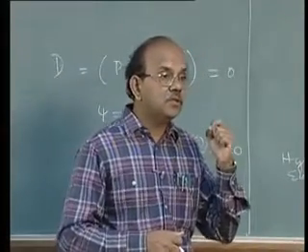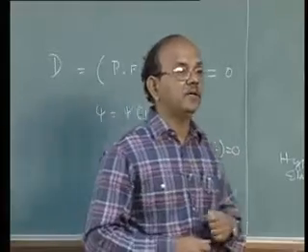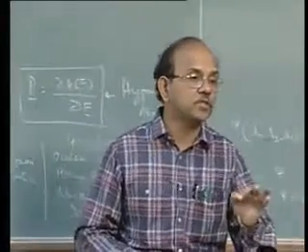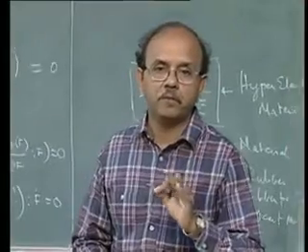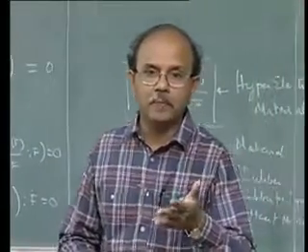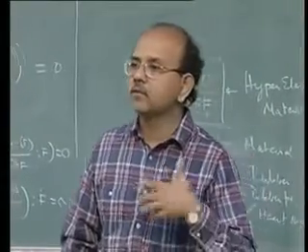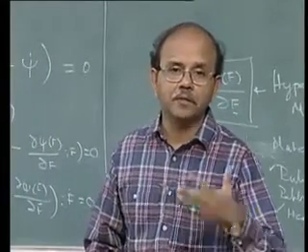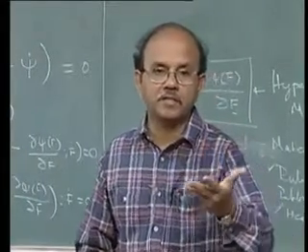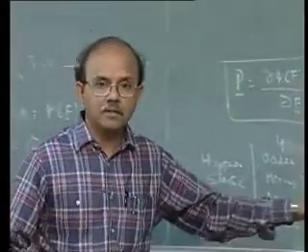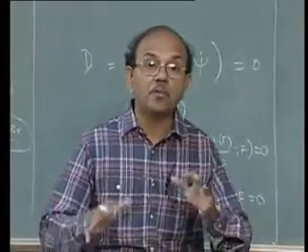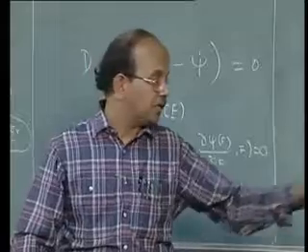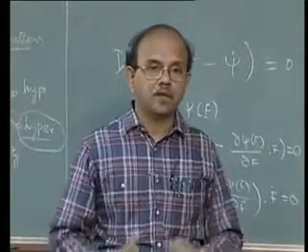So when you take a material and want to analyze it using nonlinear finite elements, the first thing you should do is ask: how do I represent this material? Suppose you look at packages like, say, Abaqus. You will see that they have different material models to represent actual physical materials. They call this a material model.